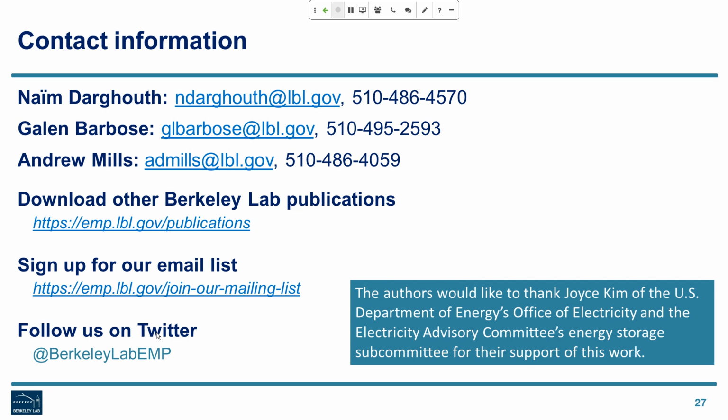When considering the dollar per kilowatt values, we're translating that kilowatt into a dollar value, and that's going to be dependent on the demand charge level in dollars per kilowatt. In the example I just gave, a $10 per kilowatt demand charge would lead to 10 times 40 kilowatts, so $400 per year of savings.